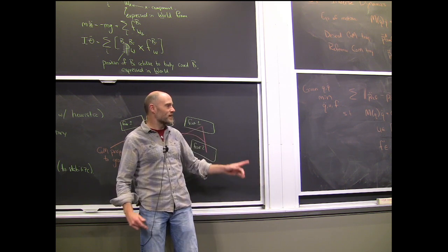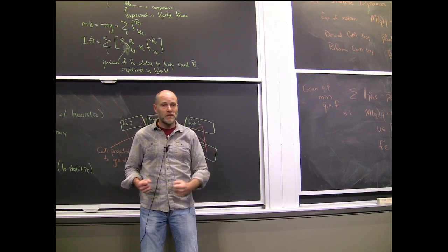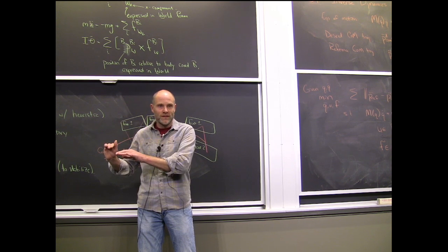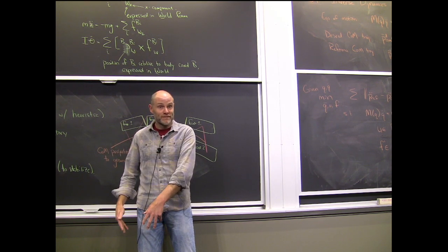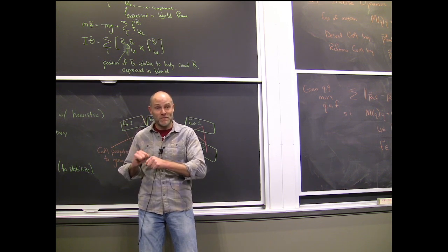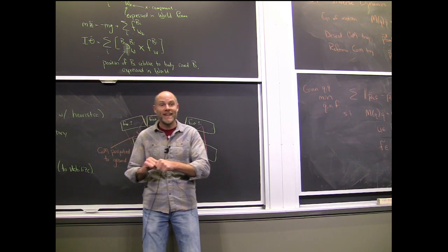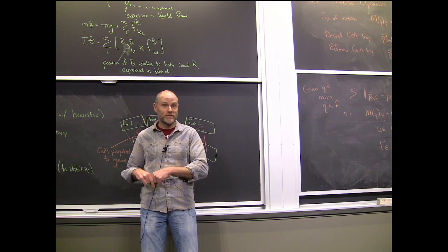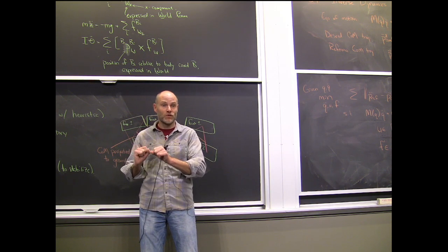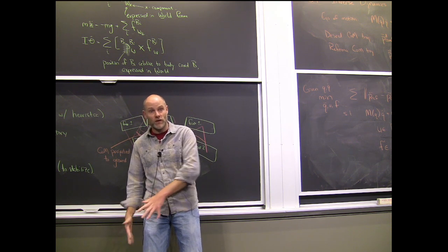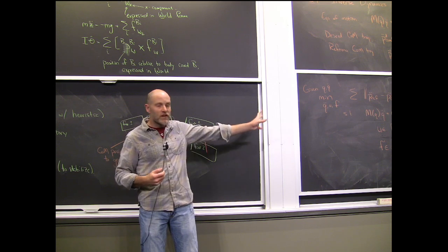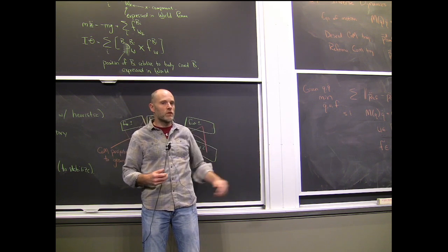The reason for that is the lesson from ZMP. People would say you need force control to control the forces of your foot, right? And that's just wrong. All you need to do is be able to move the position of your center of mass, and you are implicitly controlling the forces at your foot. That's the lesson of ZMP. You can control forces with position-controlled actuators. You don't want to do it at a joint-by-joint level. You're doing it at the center of mass level. So there are variants of this that work completely with position control.